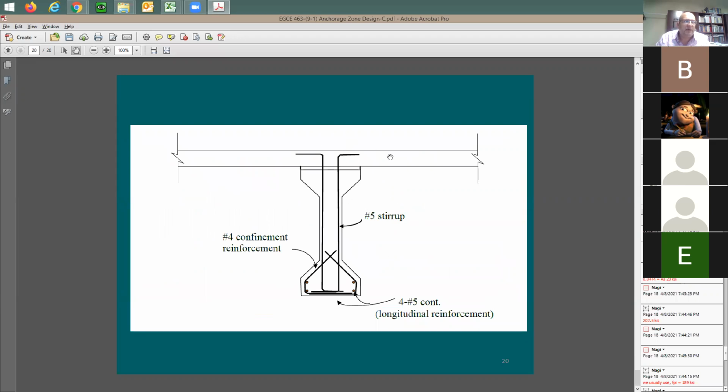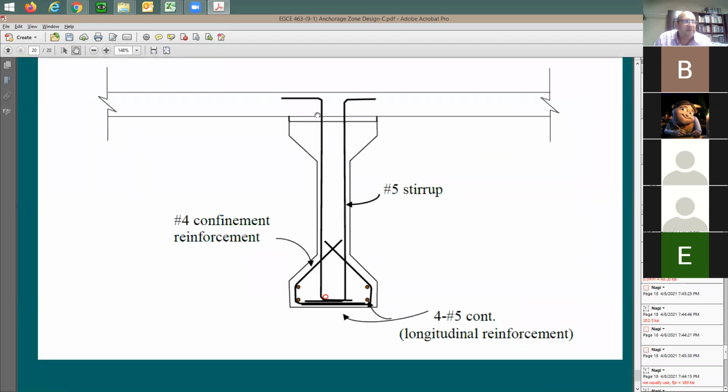Here's this section. This is the way it's going to look like. This is going to be the stirrup, and as you see here, it's going to be hooked at the bottom, and of course I'm going to have some rebars here so that this is going to be hooked around them, right? And then at the top, this is going to be the concrete deck. You're going to have reinforcement of the concrete deck, and of course your couple of bars of the concrete deck are going to be running this way. Because if you don't have an anchorage of this rebar in the top and the bottom, it means this rebar can easily slip. So you need to have an anchorage top and bottom for the rebar. So when you apply any tension to it, it's going to see some resistance.